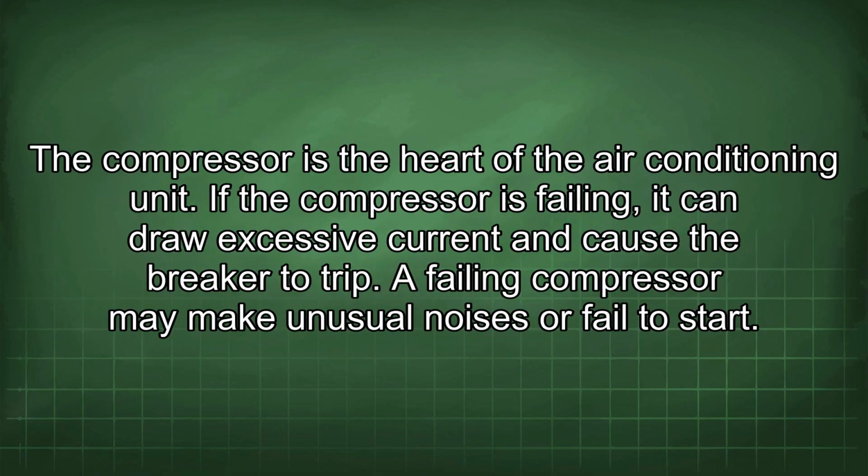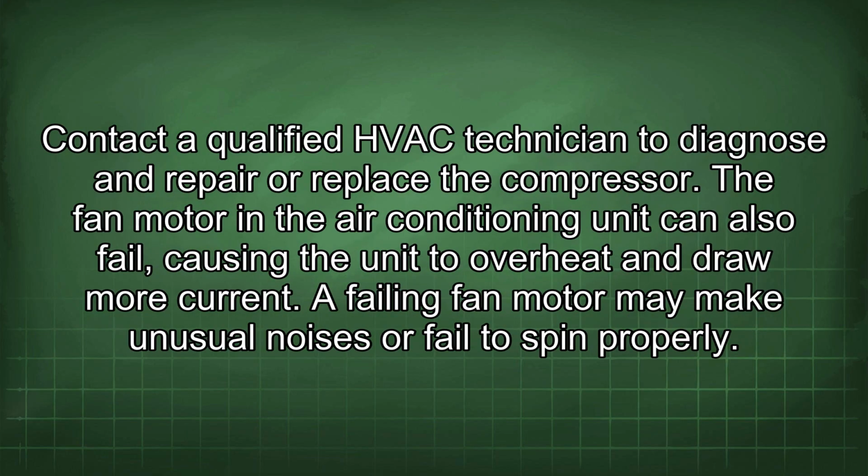The compressor is the heart of the air conditioning unit. If the compressor is failing, it can draw excessive current and cause the breaker to trip. A failing compressor may make unusual noises or fail to start. Contact a qualified HVAC technician to diagnose and repair or replace the compressor.